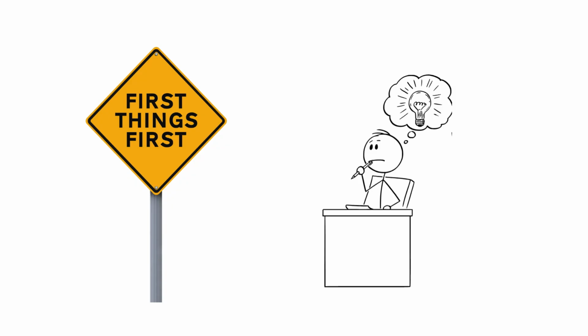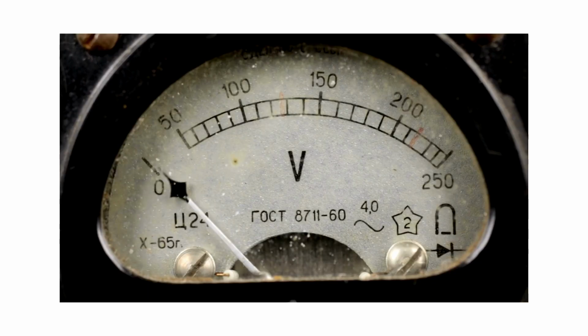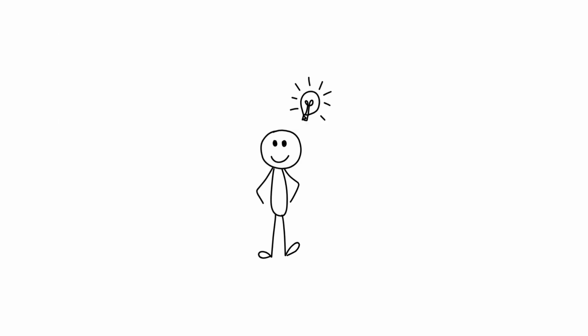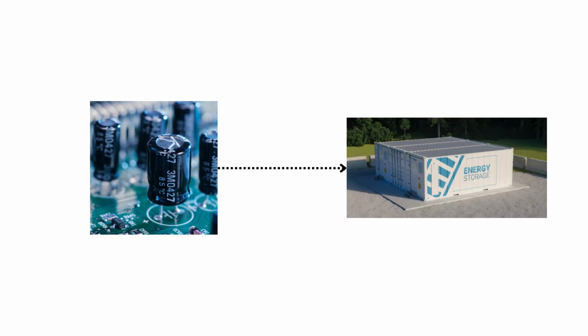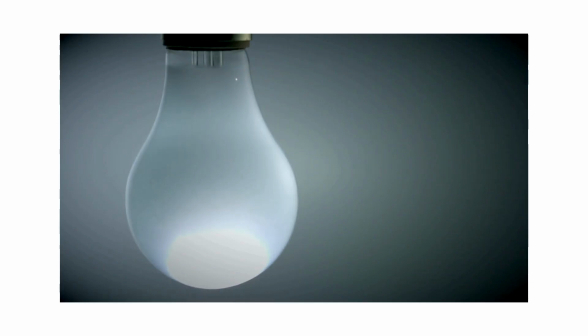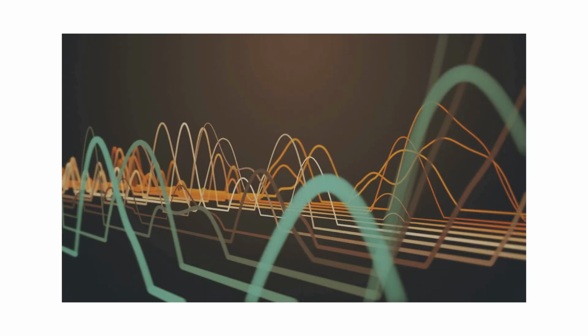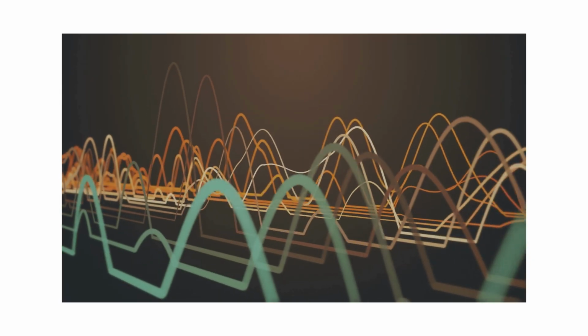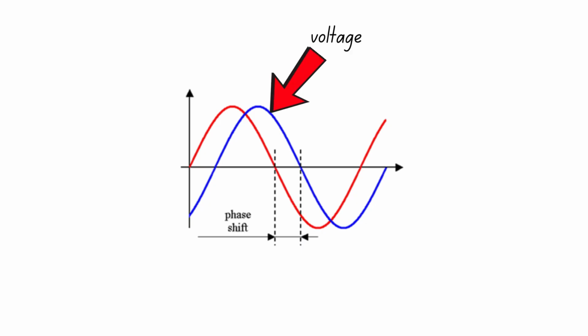Well, the first thing to notice is that the capacitor will continuously charge up and discharge as the source voltage and circuit current continuously change direction. As you now know, capacitors store energy during charging and release it during discharging. This means that capacitors are cyclically absorbing and releasing energy within the AC circuits to which they are connected. This causes capacitors to alter the phase between the voltage and current within the circuit, meaning that they no longer reach their maxima and zero values at the same time.